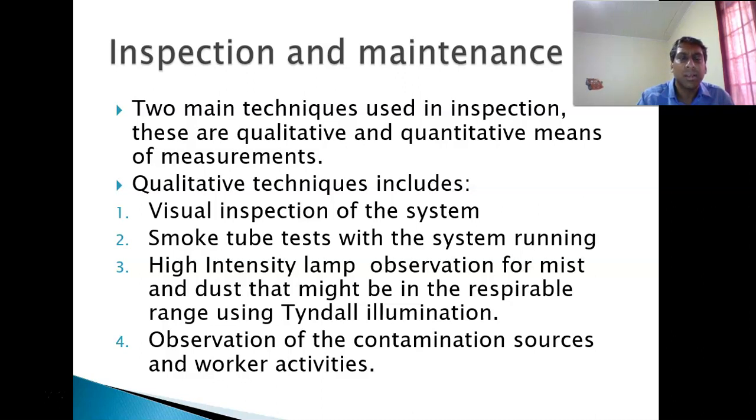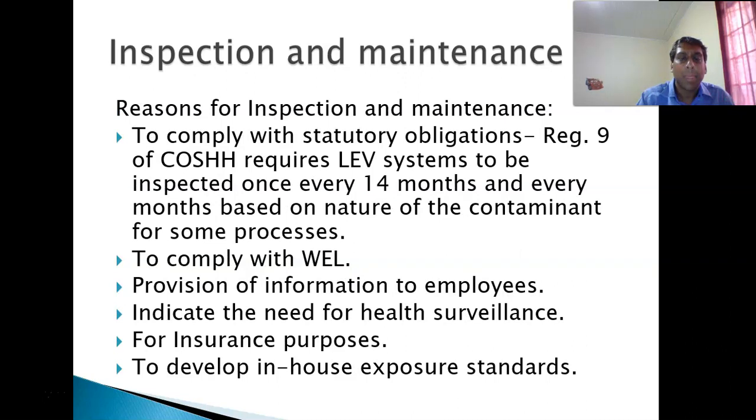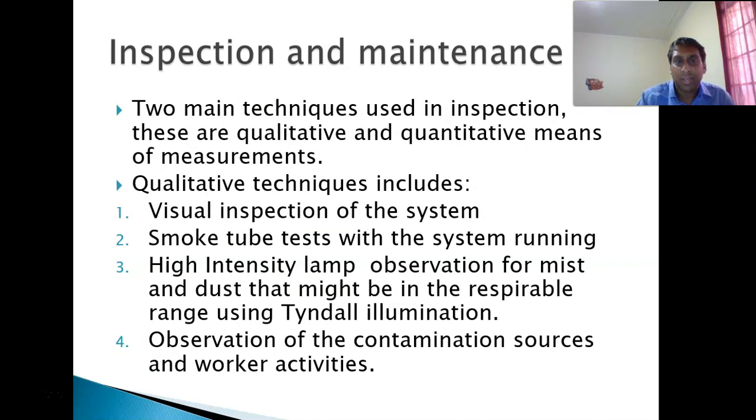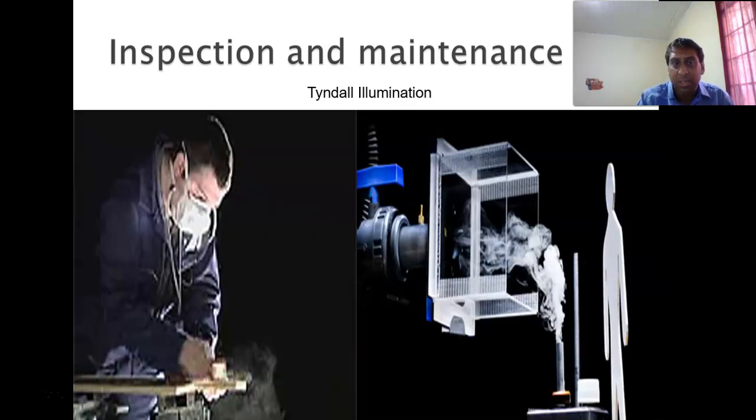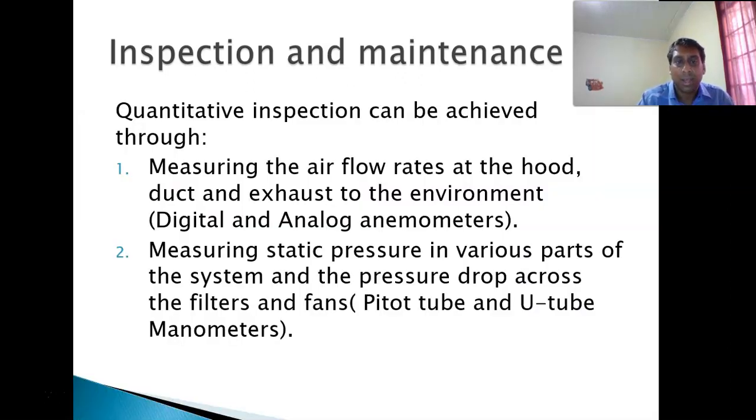So, measuring airflow rate by the anemometer, and then you see static pressure. We have used the word kind of haphazardly before, but static pressure is the force of the air that's acting on the inside of the LEV system, and this Pitot tube is able to measure that static pressure. In fact, the crude version of it is really not able to measure static pressure directly. It is actually able to give you two readings which you can use to find the static pressure.